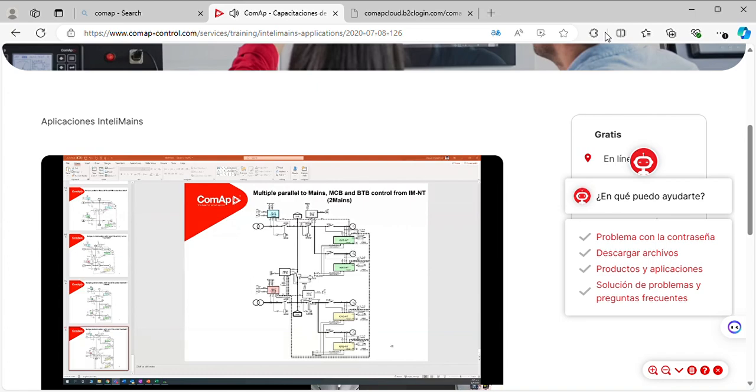Now, say for example, if my genset number 4 broke down, or there is some maintenance going on, so I would stop, say, the 4 genset. Now my one genset is too overloaded and I don't want it to suffer alone. So I can close the bus tie breaker. That means I'm clustering these two gensets with my second powerhouse by combining this bus tie. Before I do that, because this is a live bus from the first half and the second half, these two generators are feeding the left bank and the single genset is feeding the right bank.